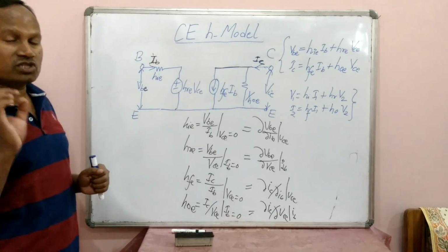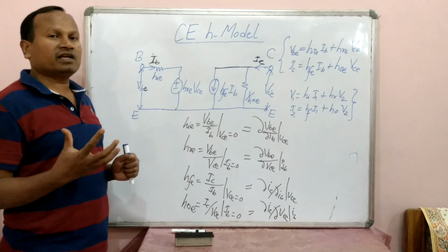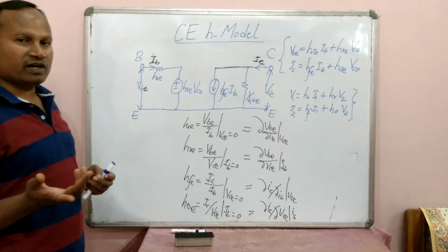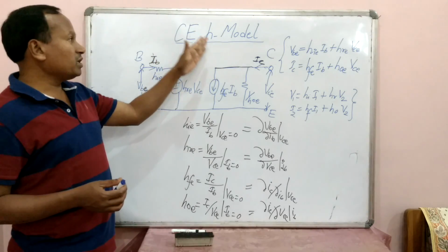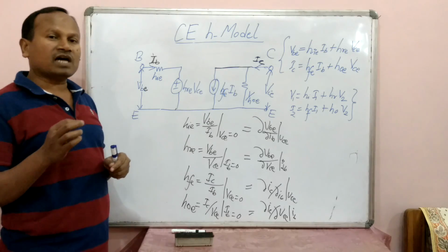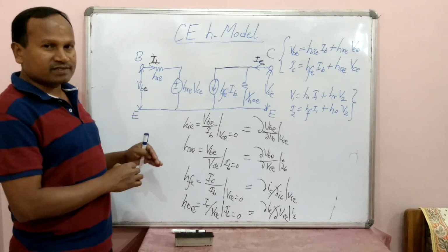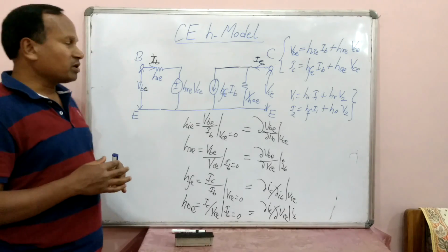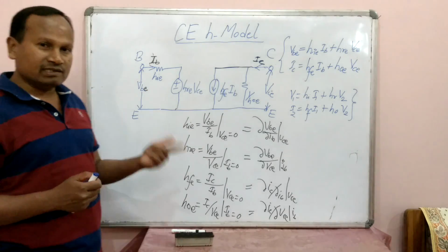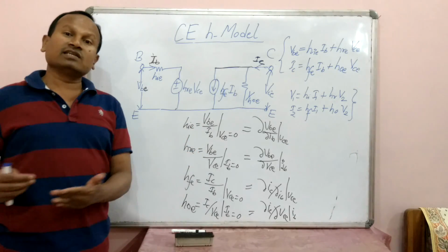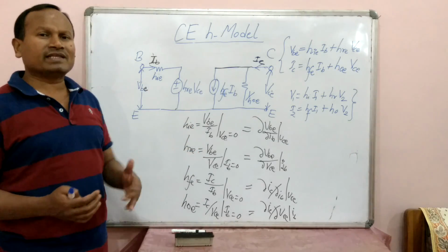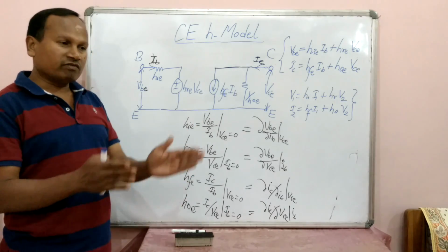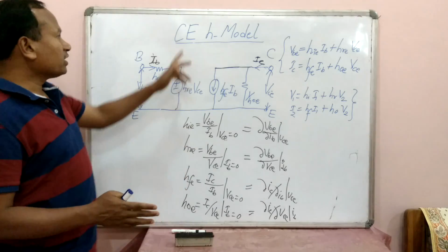The common emitter amplifier is the most important amplifier used in most applications. When we compare common emitter, common base and common collector, the common collector gives the highest current gain but the lowest voltage gain. Similarly, common base behaves in reverse to common collector: the voltage gain is highest, but the current gain is lowest. So we normally don't prefer where extremities are there. We prefer medium to high values for both voltage and current gain, which are there for the common emitter amplifier.